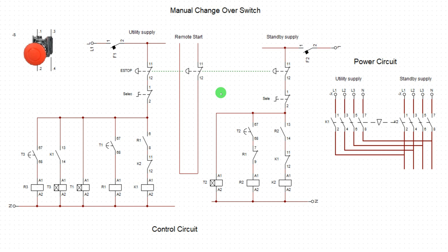Now, we are going to go into the digital panel to find the terminal, how to identify the terminal for the generator that you're going to use to synchronize with this. We are going to study how to identify the ATS enabled terminal on the generator. That is where this cable is going to. All right, but let's finish this aspect, then we go to that particular exercise.